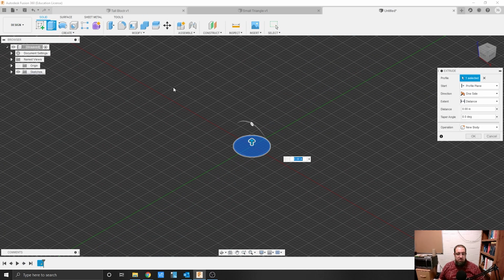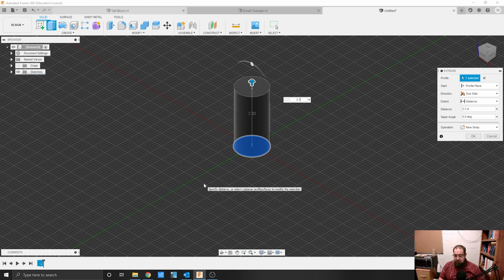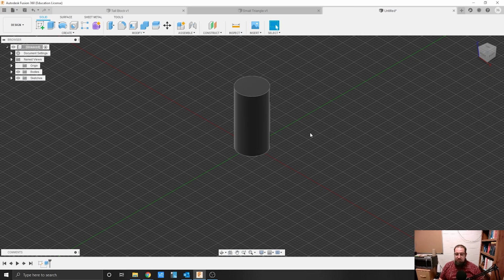And we're going to work on extruding that up, and the distance or the height of it is 2.313. Now, what that really probably is 0.3125 because that's that marker for that. They rounded it up to 313. At a later date, we'll talk about machining tolerances and why there's a big cost difference between 3125 versus 313. Okay, I'm going to put it as 2.3125. I'm going to hit enter.